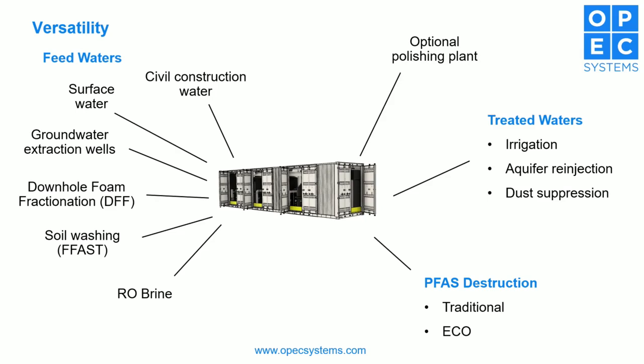So primarily we've taken groundwater extraction wells up there. We happen to have 5 of them, and we're drawing out PFAS contaminated water and directing it to the SAFF. But certainly that's not the limit to the technology. You can use the same system on the same site for surface water treatment. So if you've got water accumulating in culverts, or in on-site retention dams, you can of course direct that back to your SAFF plant and treat it.